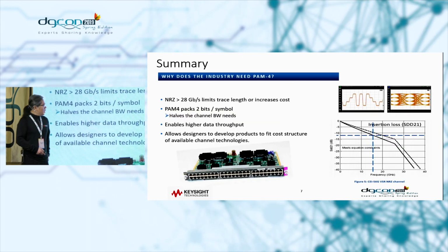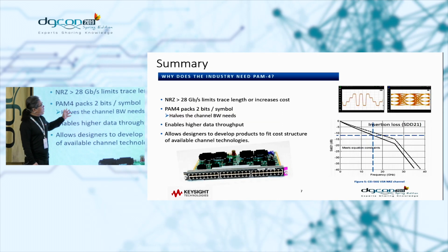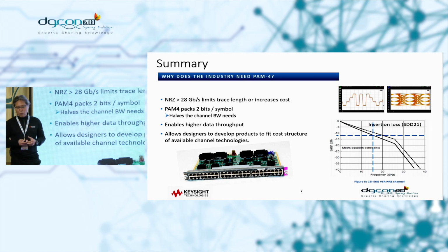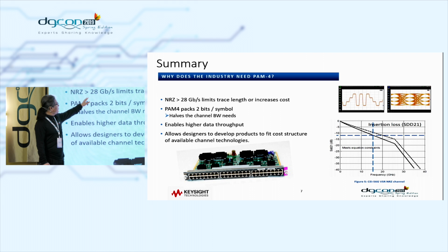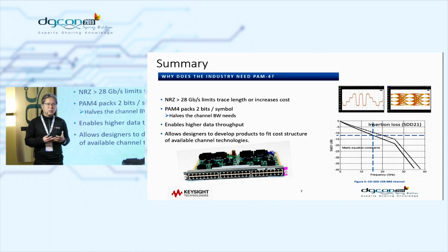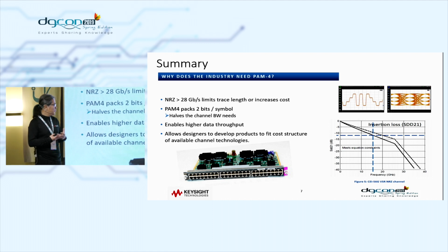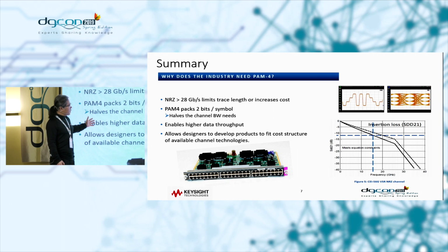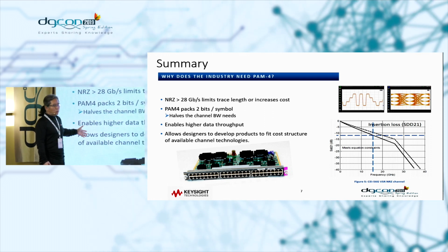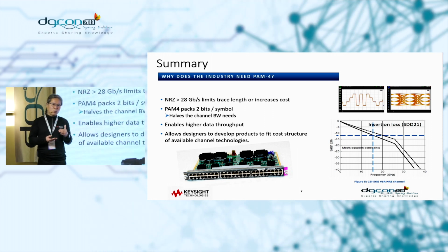So as a summary, why people are moving to PAM4 is because of the speeds: higher throughput for the system by using the same transmission line structures. But along with that benefit, we also need to think about the smaller noise margin.